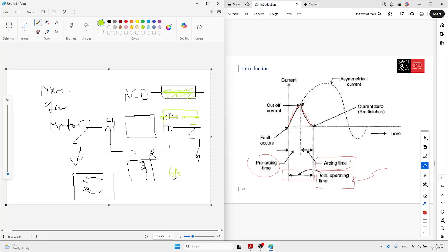Can we use a 5 amp fuse? We cannot. Why? Because at normal operating condition, after a while, it draws 6 amp, and the 5 amp fuse will be blown and burned out. So step one, we should choose the best current, close to the operating current.